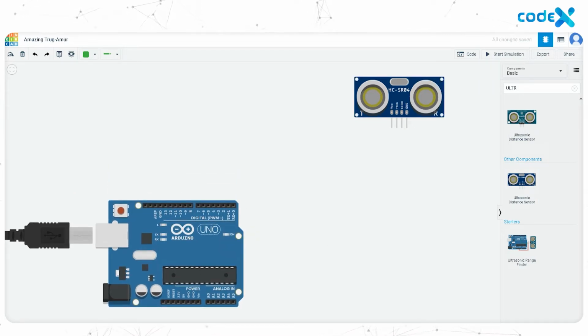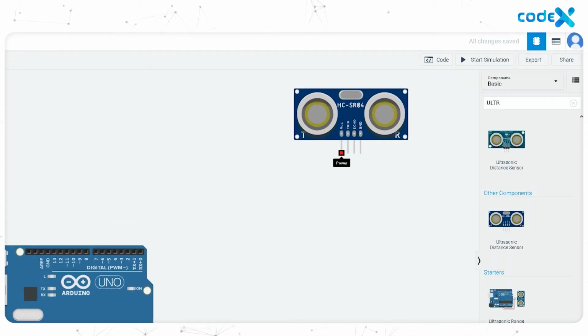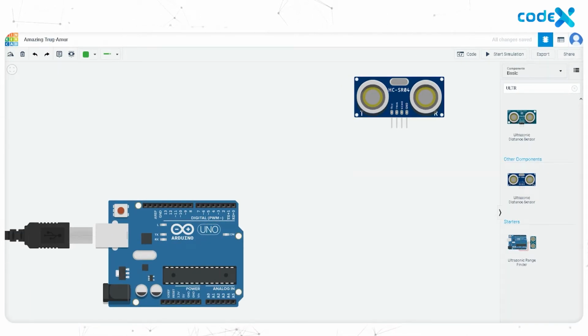So this is the ultrasonic sensor. Can you see the 4 pins of the sensor? They are VCC, trigger, echo and ground pin. Just like any other component, we need to power up the ultrasonic sensor to make it work. And ultrasonic sensors can be powered using the VCC and the ground pin. Now, the trigger pin is the one that emits the ultrasonic waves. These transmitted sound waves hit the target, then bounce back to the receiver of the sensor. And from the echo pin, we can obtain the output.